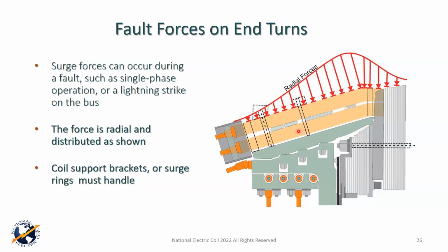So on 60 cycle machines, if something is twice 60 hertz, within about 115 to about 135 hertz, that's what we call the exclusion zone. It's going to have some degree of resonance, and the closer it is to 120 hertz, the greater the resonance, and the greater the resonance, the greater the vibration that's exhibited. So I hope that helps you with that, Franco.